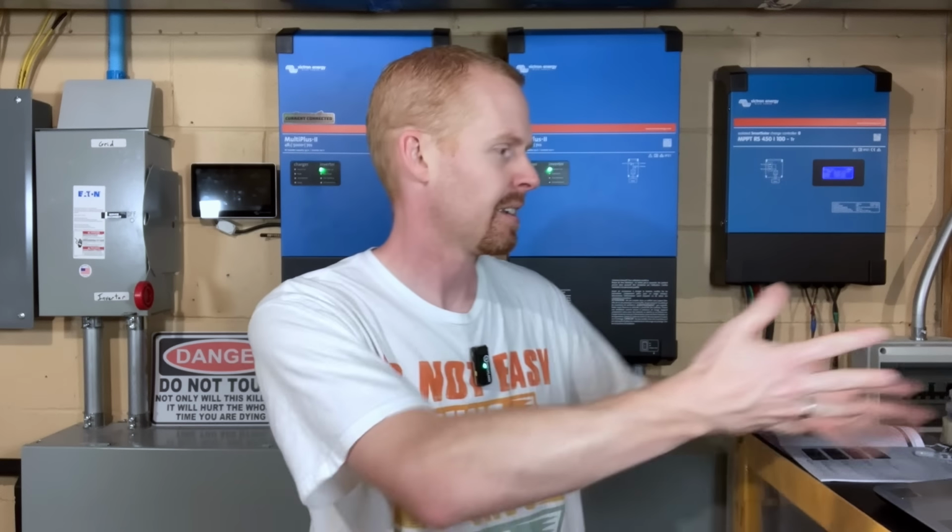The virtual switch and the assistant worked great for me for a time, but I found that, well, what happens if I want to tweak the values at all? What happens if I want to raise my state of charge values? I don't want it to get down to 15%, or I want it to be on grid longer than, up to 30% state of charge. And so I started looking into things because I didn't want to have to get into the software and make the software changes every time I wanted to tweak the values a little bit.